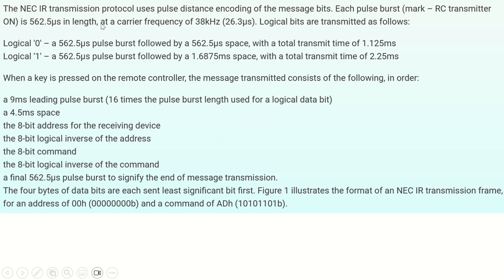All right. So there is what is called an IR transmitting protocol. Whenever you press any TV remote button, as I already discussed, each pulse burst is 562.5 microseconds in length, and the frequency of that pulse is 38 kilohertz.